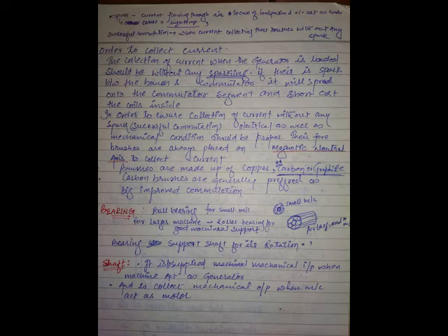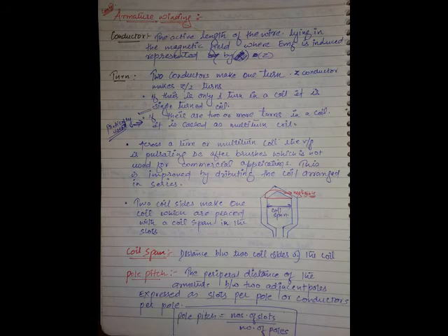Now bring this coil, this bunch. One coil side of the coil is placed in the first slot. The next coil side of the coil should be exactly placed in the seventh slot, which means you are making 6 slots as coil span. Between 1 and 7, how many slots are there? 6 slots are there.